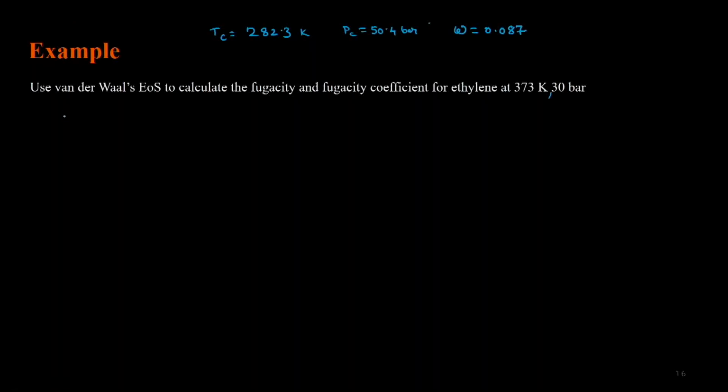Turns out for this condition, beta is omega PR over TR, and this value turns out to be 0.056312. Q is psi alpha by omega TR, and for this particular case the value turns out to be 2.5543. Remember, alpha for van der Waals equation of state is 1.